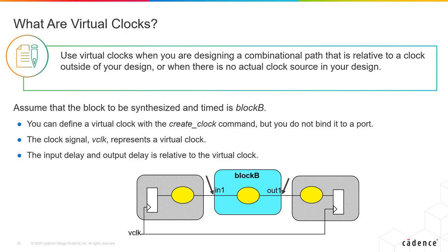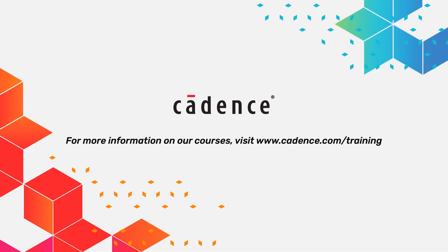The output slew degrades as the clock signal propagates through these cells. Because these virtual clocks do not have a port association, STA tools keep track of these in your design. You can just use the create_clock command without binding it to any port or pin. After creating the ideal clock, you need to refine it with specifics. So if you want to model the real nature of a clock, you need to add the transition times.